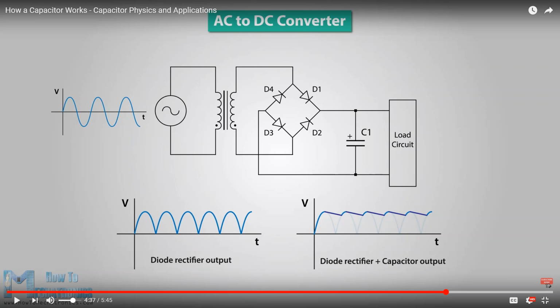So what a capacitor will do is that during that short period where the voltage drops, your capacitor is discharging. And during that time, between here and here, your voltage is recharging. Because this happens so quickly, your capacitor is constantly charging and discharging to make sure that you get a flattest amount of voltage or the most constant source of voltage possible. Okay? They're hugely important, right?